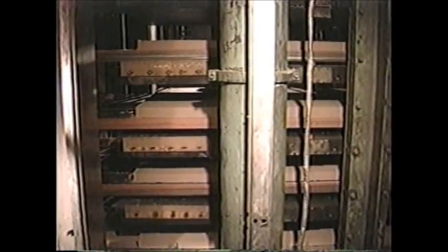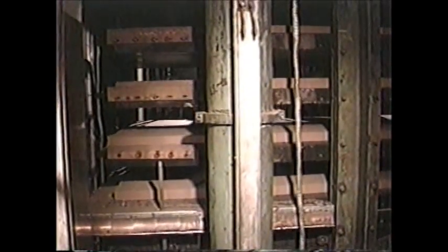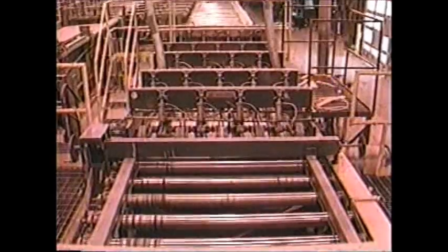When the trays are loaded and the press opens, the press openings are simultaneously loaded and the newly pressed panels are pushed into a similar set of trays on the opposite side of the press. Panels enter the press at a moisture content from 8 to 9% and exit at about 3%. The hot press uses a combination of steam heat and radio frequency energy to cure the panel adhesive in a cycle lasting from 3 to 4 minutes.